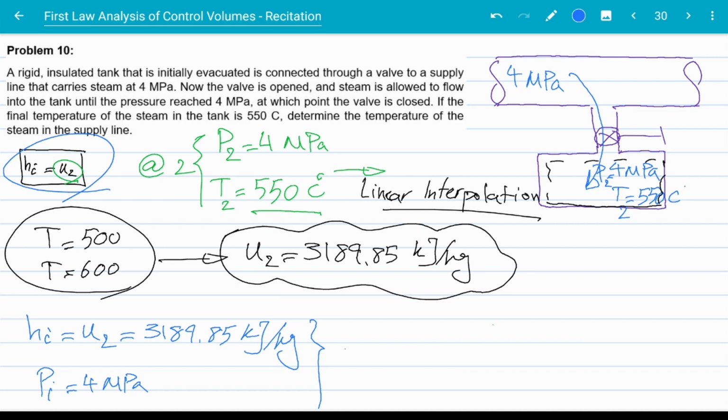So let's go to the superheated steam and check with that. We'll see that the H that we have is larger than the H of 350 degrees Celsius and is smaller than the H of 400 degrees Celsius. So again, we don't see the exact number in the table. We need to do a linear interpolation.